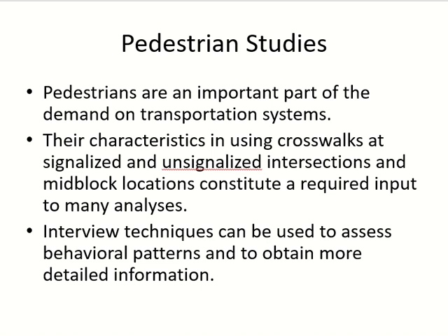Then we have pedestrian studies, obviously for pedestrians, and why they are important, because they are more likely to get injured during accidents. So you have to make sure that they can safely use the highways. Where are they using the highways? When they are mainly crossing. So you have to provide them safe locations for crossing. It can be at the same level, or you can make elevated pedestrian bridges, or underground as well. But you have to know their number, the time they need to cross, the location where they want to cross.